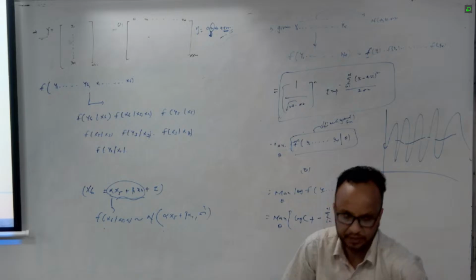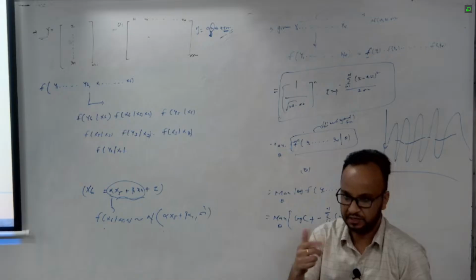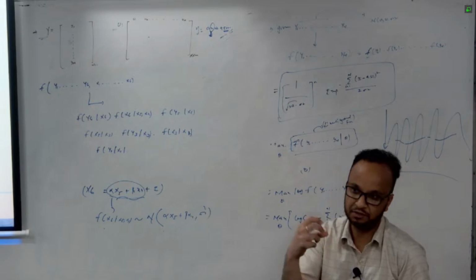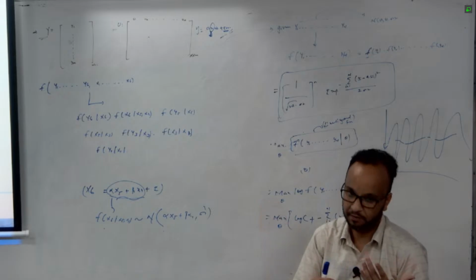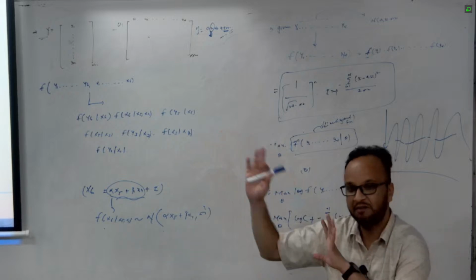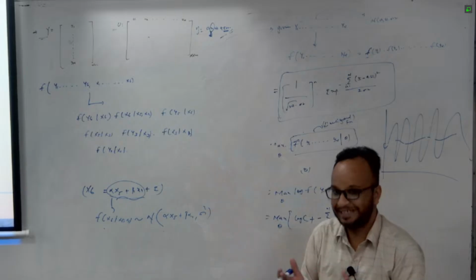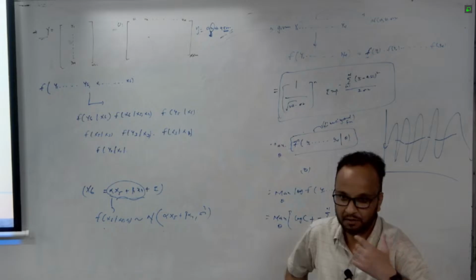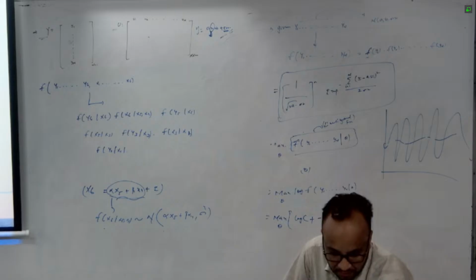Actually, in the case of chemical engineering, say you are taking one particular sensor and your hidden variable is something you don't know, hidden inside. You need to estimate the hidden value theta because the actual sensor is giving noisy readings. I want to estimate the hidden theta. So how do I estimate it? One way is filtering, Kalman filtering. Actually what we are doing is kind of Kalman filtering only. It's a data-driven Kalman filter, kind of. If you actually derive every equation, you are going to get a nice Kalman filter, a steady state Kalman filter. Those who have an idea of the Kalman filter can appreciate it.